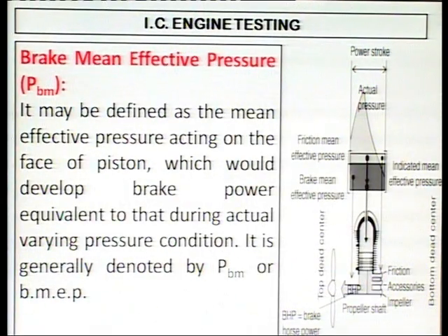Next is brake mean effective pressure. It may be defined as the mean effective pressure acting on the face of the piston which would develop brake power equivalent to that during actual varying pressure conditions. It is generally denoted by PBP or BMEP, brake mean effective pressure.